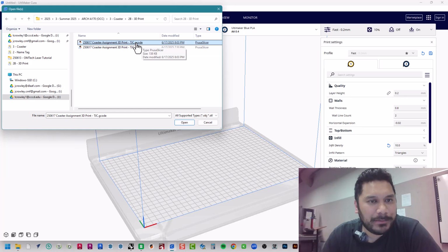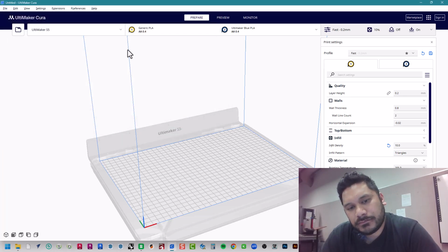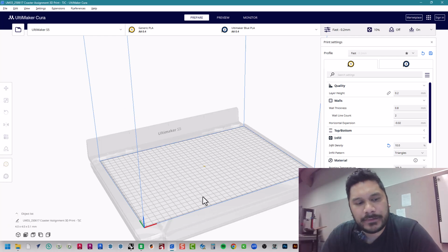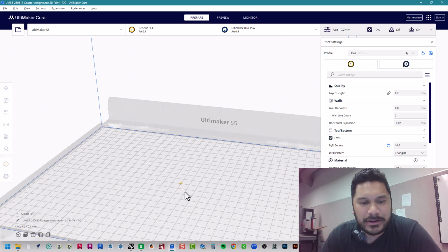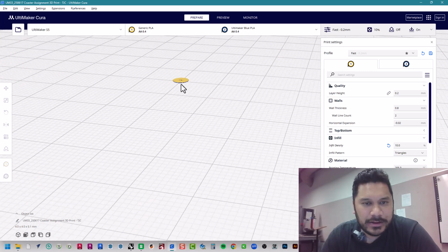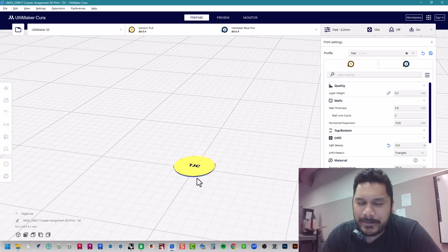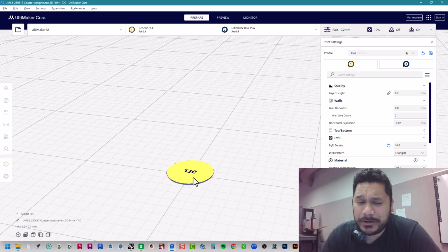Here it is. Remember the issue that we had previously with Bambu? One of the first things it asked us was, hey, are you sure you didn't mean imperial units? Because I can scale this for you to millimeters, because I've imported this as 4 units, which in my world is 4 millimeters. So the size of this thing, if I go to scale, is 4 millimeters, which is completely wrong. So a couple things you can do when you're in Rhino and you're 3D modeling.